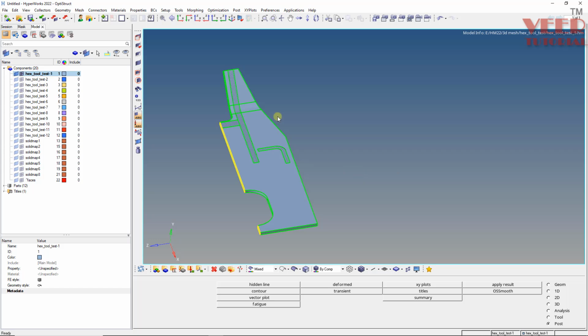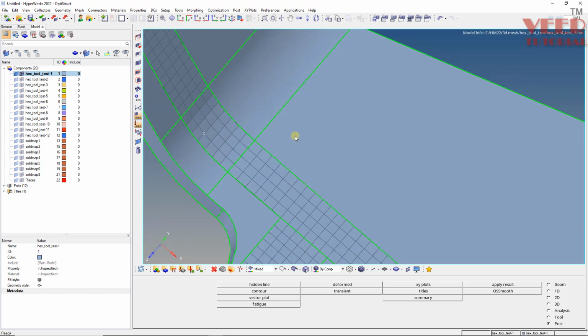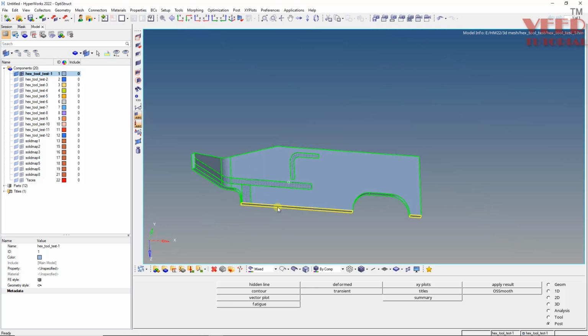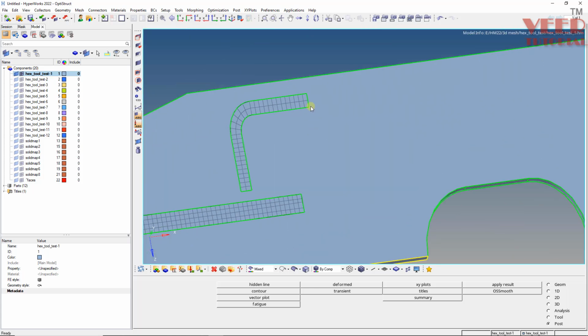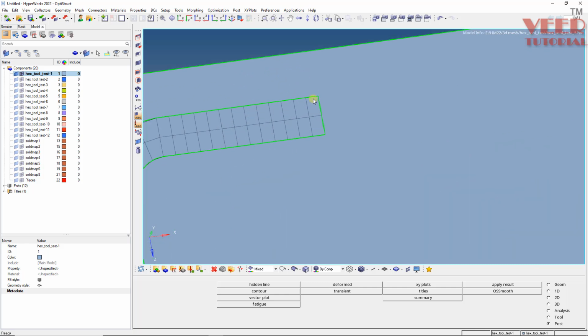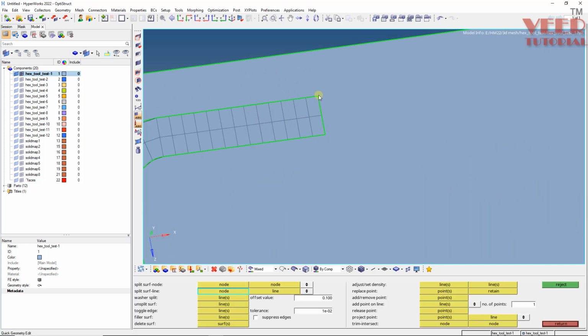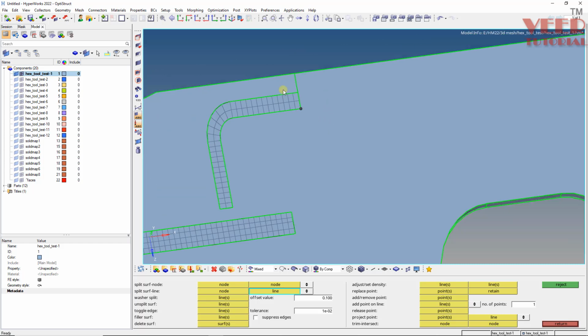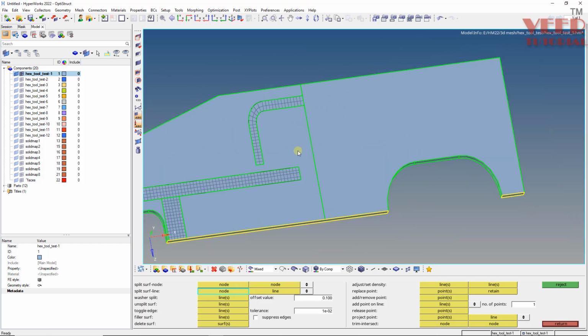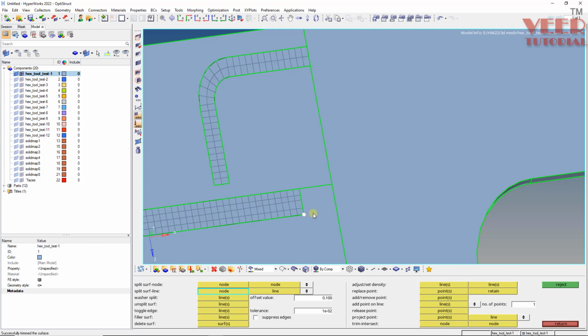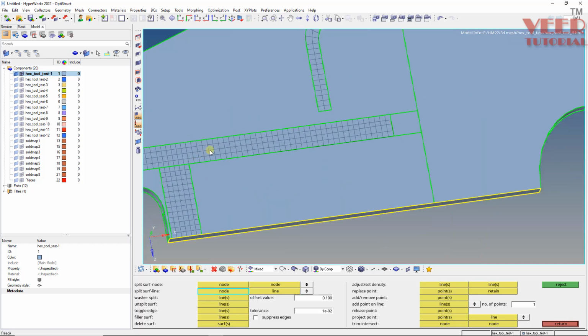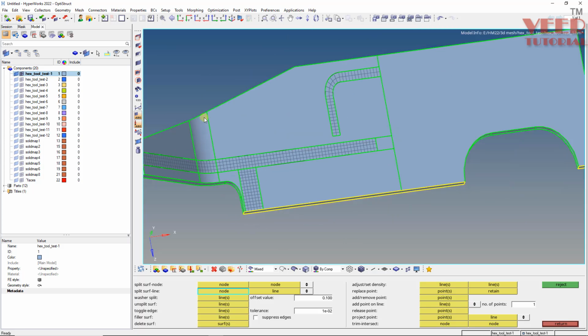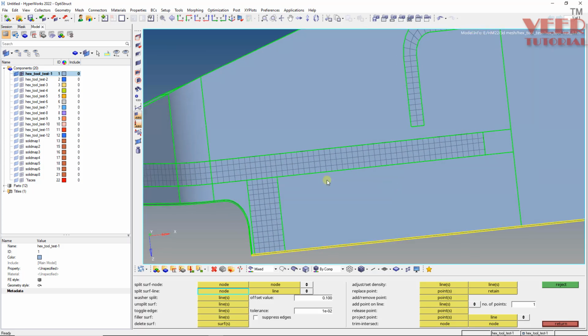So in this part we are doing the meshing of this bottom plate. You can also open the Xmesh file number 5 for the reference, and we have taken the mesh in this component. Okay, so now we just have to do the meshing of this with proper connectivity. So F11, and let's say I will make a split here up to here. Similarly, one more split here to here. Okay, so now let's start the mesh.